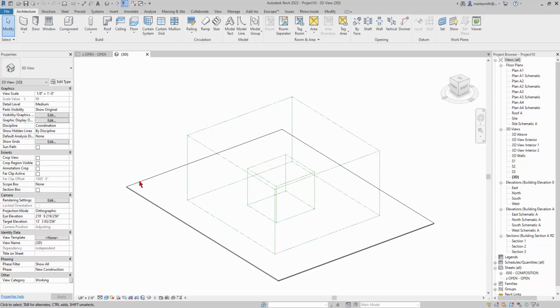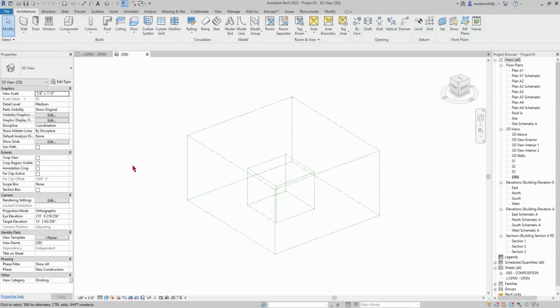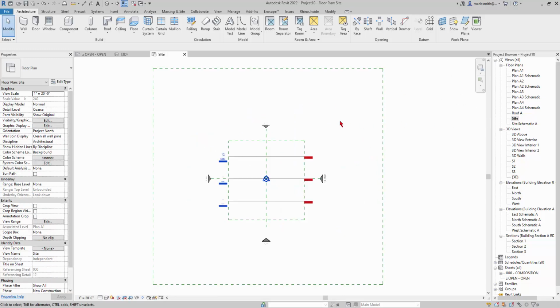It just has views and sections and sheets set up for us. I'm going to go ahead and delete this floor right now. We can put another one in later if we need it, probably won't. And then what I'm going to do is link those drawing files that we created into here and work on updating their materials. All right, so go to your site plan. This is where I typically like to be when I import things.